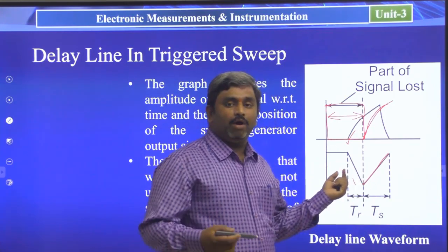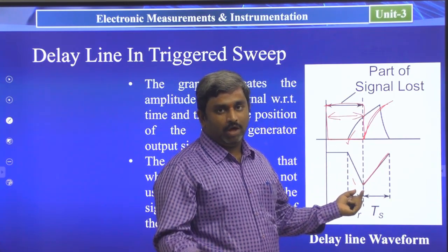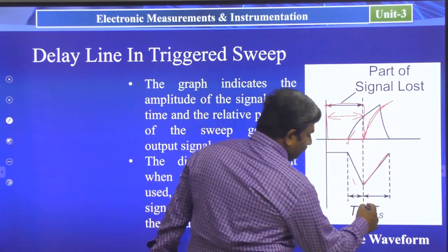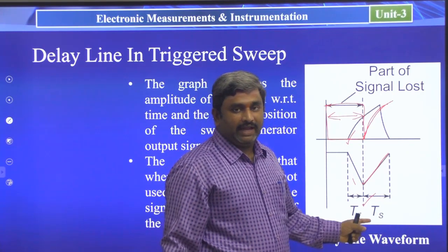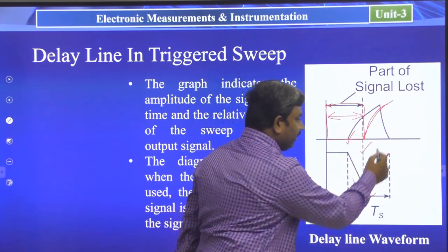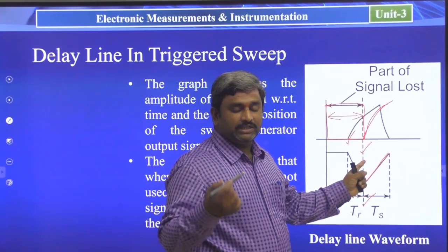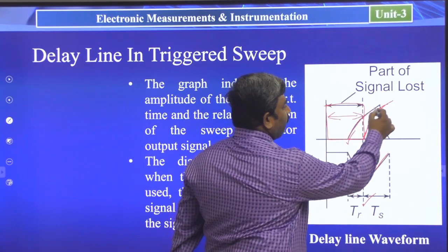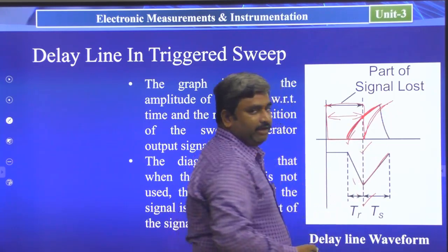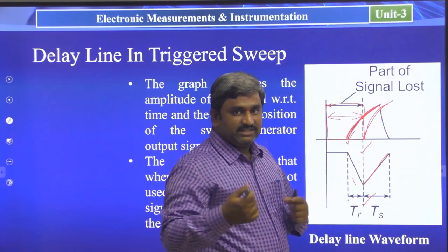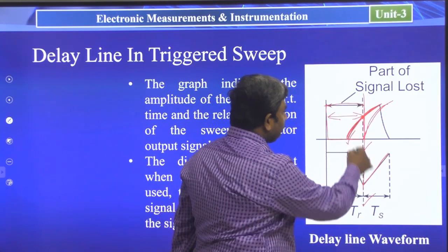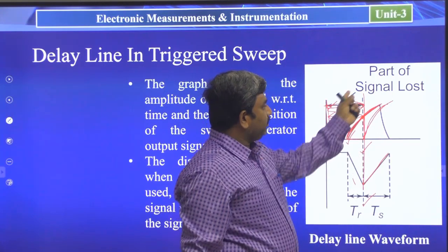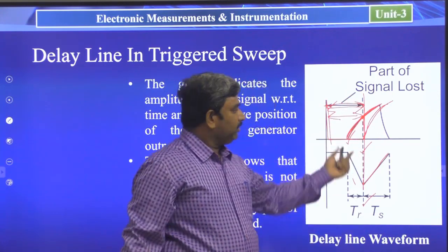We are not getting the horizontal information yet, but the vertical information is going to start the display. Here the sweep period is started in the time-base generator. The received signal time period actually started here, but the vertical direction signal was already displayed before. So the system will not take the signal up to here, and for that reason this part of the signal we are losing.